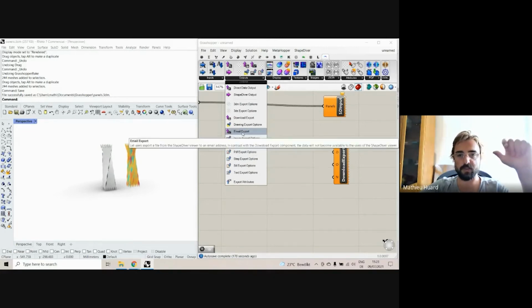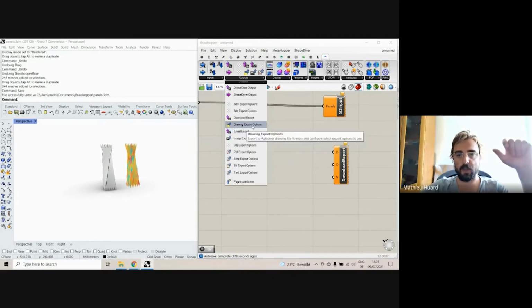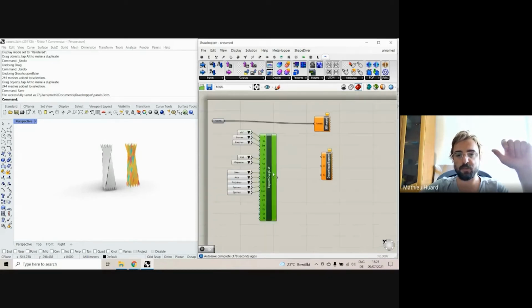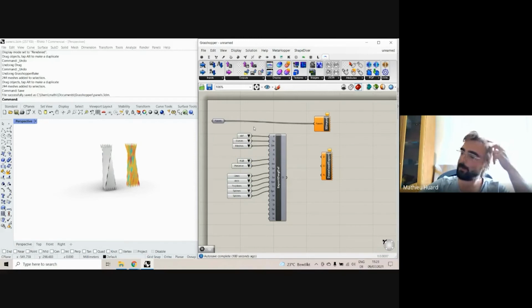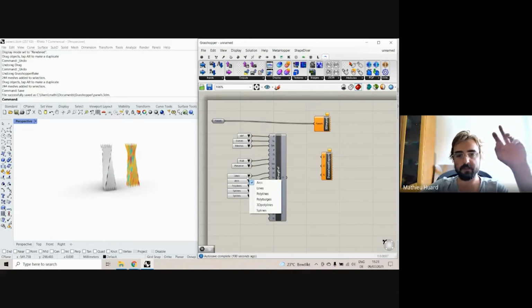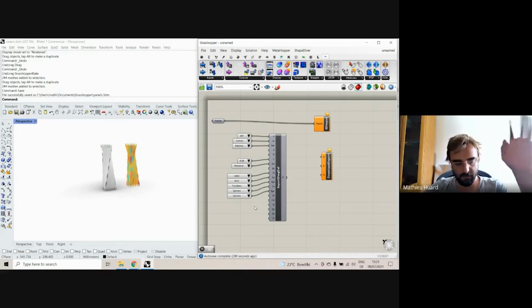For the drawing export options, for example, now we support all of those. That used to be an issue because we could export DXF, but if you don't set how to export lines, arcs, polylines, splines, etc., then you end up with files you can't really control, depending on which CNC machine is going to cut the file, for example. So that was essentially an obstacle to complete automation.